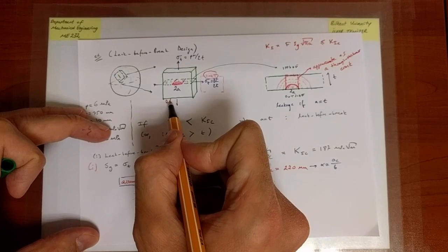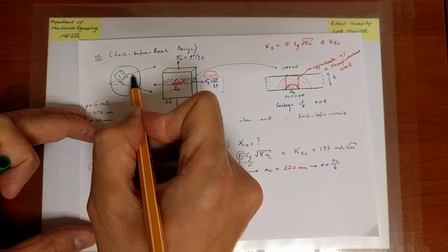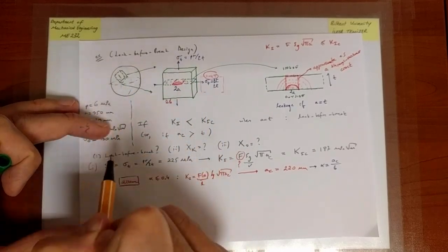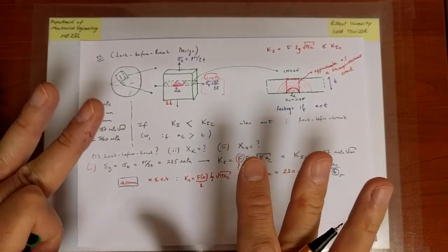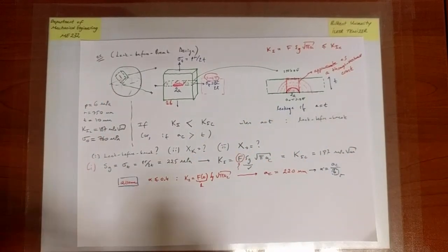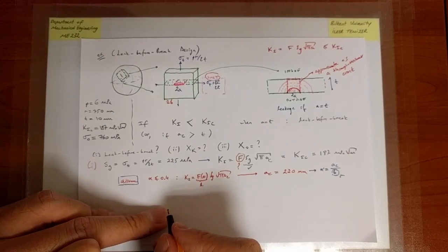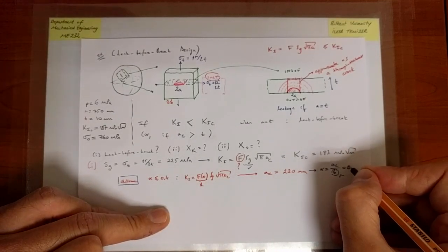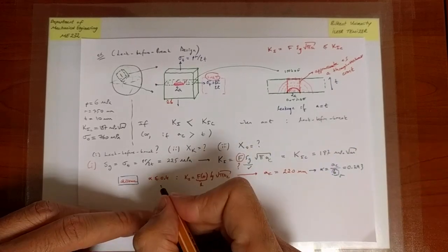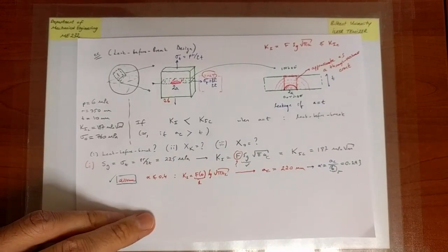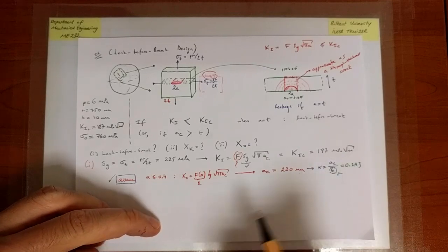So the width of the plate is a measure that has to do with the in-plane dimensions of the sphere, and the in-plane dimension, if you like, has to do with the circumference, and the circumference is a function of the radius. So I'm going to take B to be the radius. Now, this is a very shaky argument presently, but I'll take B to be the radius as a measure of some reasonable in-plane dimension. In that case, you will obtain alpha to be 0.293, 220 divided by 750, which is less than 0.4, and therefore my assumption was fine. I am within the 10% limit on F, and therefore the value I have calculated is safe within that assumption.